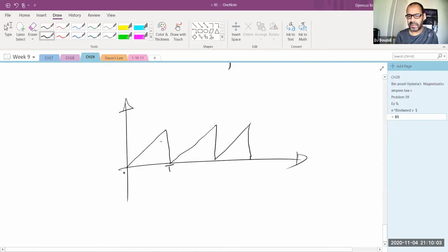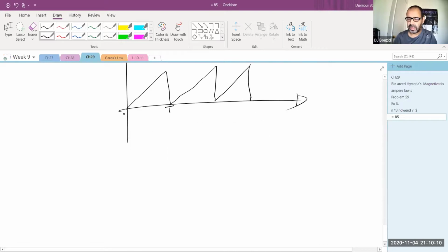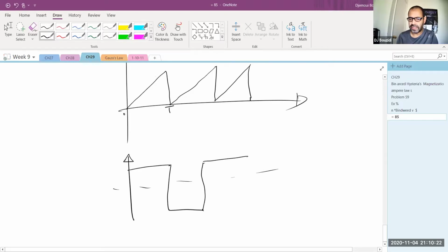So if I'm going to find the RMS again, I'm going to square this value and then average it. Or I can give you another signal that turns on and off by itself, like a square signal, and then it's shut off or goes to a negative value. It's going to be positive for half a cycle, then it's going to be here, and so on and so forth. Obviously, the period of this signal is from here to here, and I have to, again, find the average for this signal.